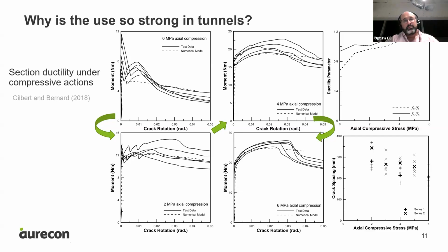And we increased to 4 MPa on the top middle corner here, a middle column. And the capacity not only increased from close to 12 to 14, but it has increased now. The peak values have increased to somewhere just above 20 newtons per meter. And you see post-cracking a little bit of hardening, it reaches a peak and then starts a descent. And as we increase again, the capacity increases further from 22-ish, 20 to 22 to about 25.